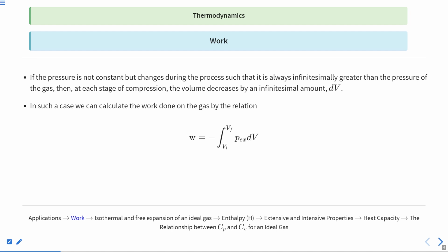So what is a reversible process? If you turn to the basic definition, it is a process in which from any point we can move back to the previous or the starting point. That is called a reversible process. And in that reversible process, it is required that if you are doing work, you will do the work in such a way that the volume change is infinitesimally small. So we take that volume as dV.